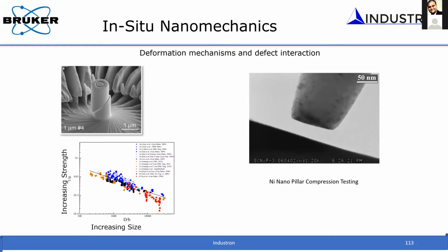This is against work hardening, because when you apply stress onto a material and you generate more dislocations, the material becomes work hardened. But in this particular case, all those dislocations were there already. They move towards the surface and they disappear, and the pillar becomes stronger and stronger. So Nix at that time at Stanford came up with this and explained it beautifully with these results. The reason why the strength goes up is mainly because the dislocations have a characteristic distance that they have to move before they multiply, right?